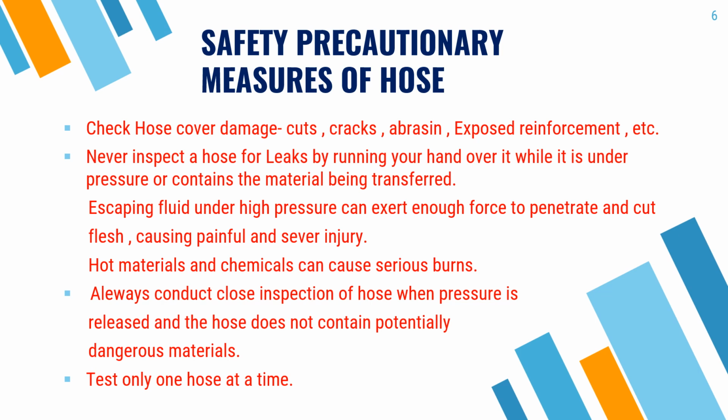Never inspect a hose for leaks by running your hand over it while it is under pressure or contains the material being transferred. Escaping fluid under high pressure can exert enough force to penetrate and cut flesh, causing painful and severe injury. Hot materials and chemicals can cause serious burns. So that's why we should never do the leak test by running our hand over the hose.